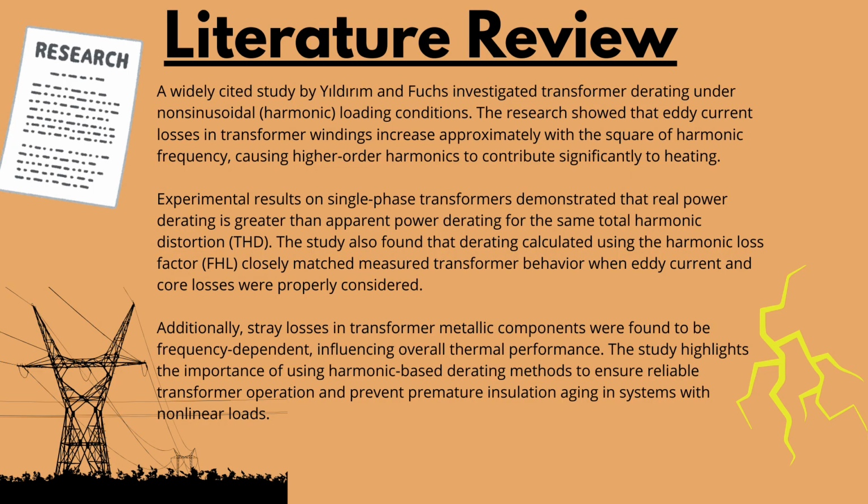I'm going to talk about literature review. A widely cited study by Yildirim and Fuchs investigated transformer derating under non-sinusoidal harmonic loading conditions. The research showed that the eddy current losses in transformer windings increased approximately with the square of harmonic frequency, causing higher order harmonics to contribute significantly to heating. Experimental results on the single-phase transformer demonstrated that the real power derating is greater than the apparent power derating for the same total harmonic distortion, which is called THD.